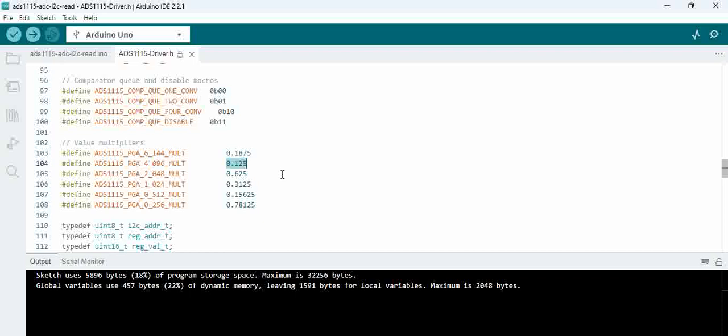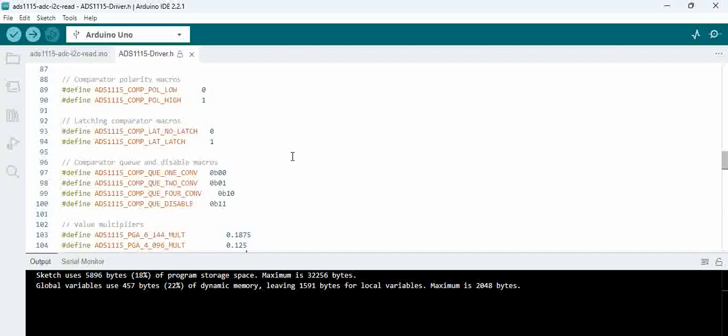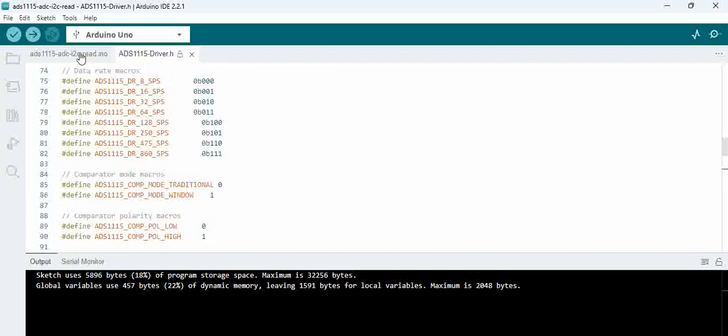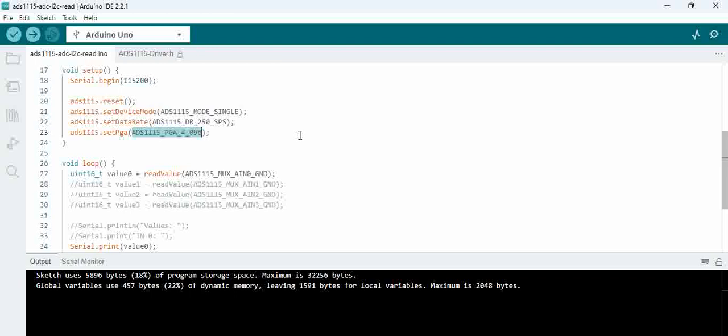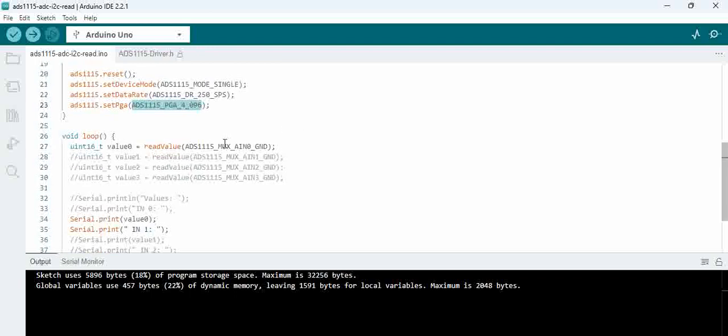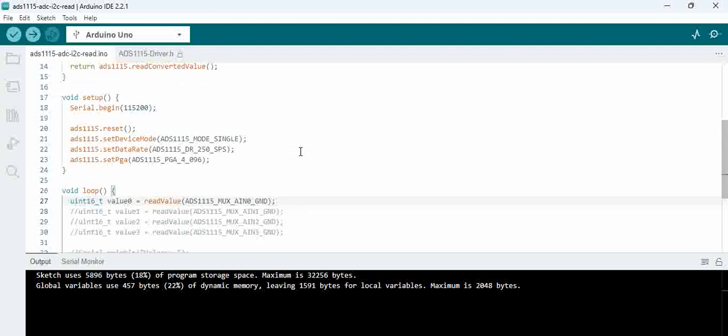If you are giving higher analog values at the input, or if you are expecting from some sensor higher values, use as low gain multiplier as possible, so that would not saturate your sensor and give higher values. And while reading, ensure that you read the correct analog input and not the wrong input. So that could be one more problem.